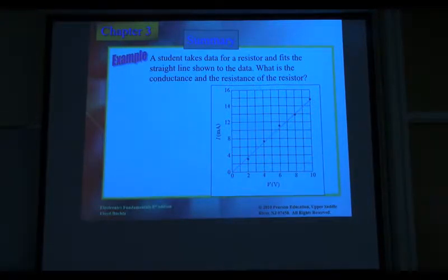So I will read the voltage here equals 0, current equals 0. This one, the voltage equals 10, the current equals maybe 0.15, so 14.8 maybe. The resistance will be equal to the voltage change divided by the current change. So from here to here, the change of current equals 14.8 minus 0, which is 14.8.